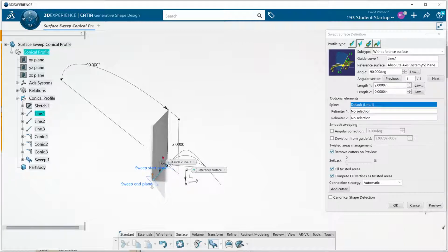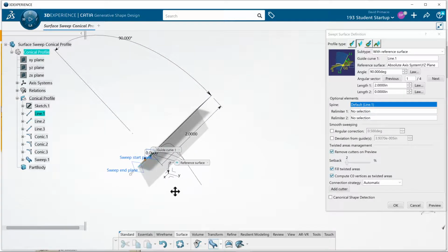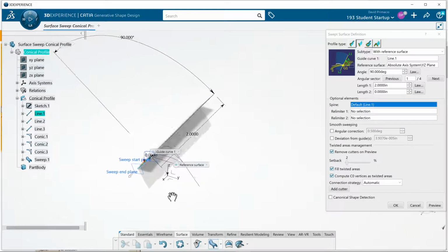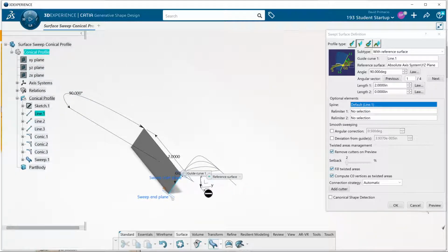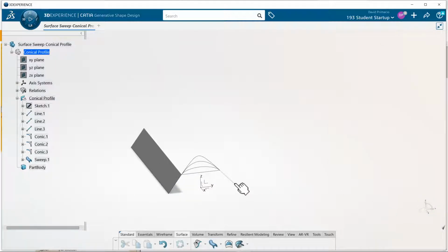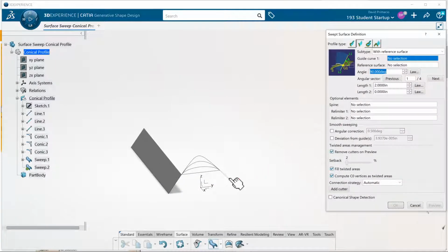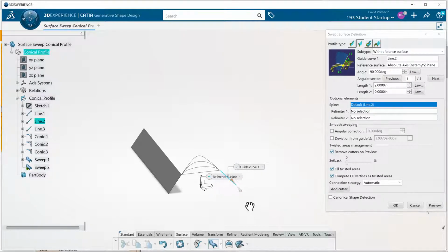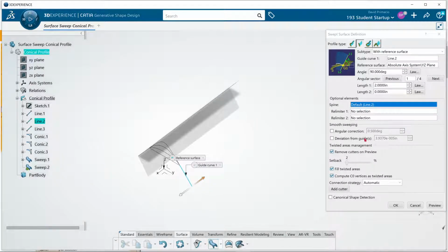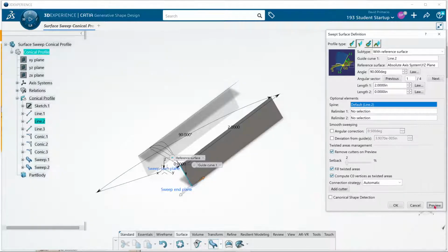and projecting it, extruding it, you have a linear surface. Basically, any way I cut this, it's a flat line, or it's a straight line. Any way I split it, any intersection I create to it, you have a line as the end result. That makes it a segment, line, or linear type surface. Alright, so it's the same thing I did in 2D, it's just that it's three-dimensional now. And I'll do the same thing on the other end using this line. So again, there's your line and there's your sweep. And then we'll select preview, select OK.